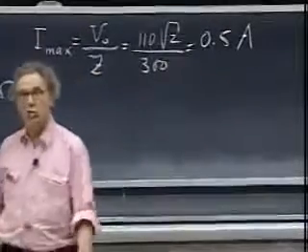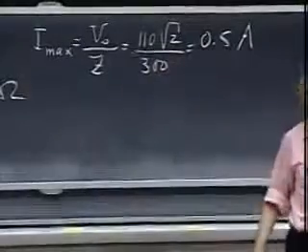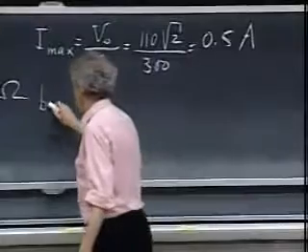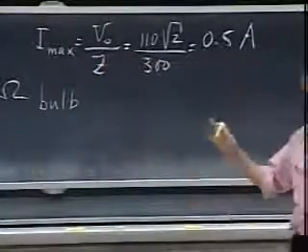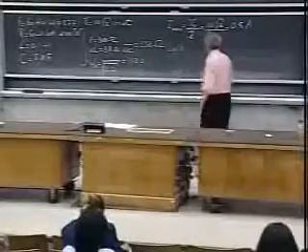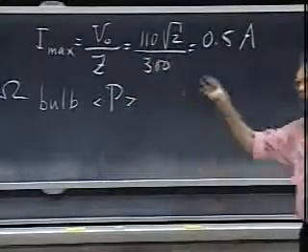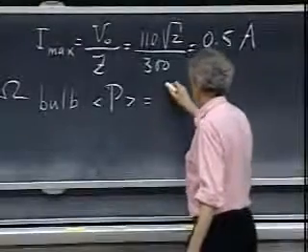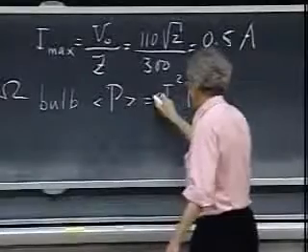And now I can tell you how much power is dissipated in the light bulb, which is I squared R. So in the light bulb, which is the only component which has a resistance, well, maybe the L has also a little bit of resistance, but we will ignore that for now. In the light bulb, the average power over one full cycle of my oscillations equals the mean value of I squared R, time averaged.